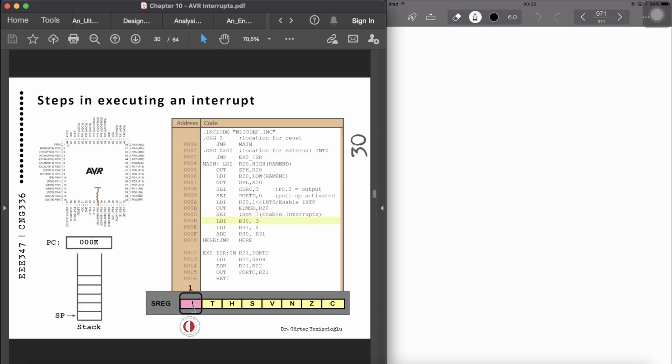Then we carry on, we initialize 3, we initialize 4, and suddenly an interrupt comes in. As you can see, as we are pulling up, when the button is pressed, that means an external interrupt event has occurred. It will short circuit to ground. Now, what will happen at this point, as we are in LDI R31-4, and the next instruction is 00F over here, which is not appearing.